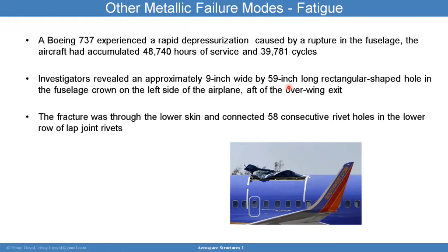And so Southwest Airlines' business model is to fly quickly, many times a day, short trips. And that's how they can make a profit compared to other airliners and also sell the tickets for quite inexpensive. As a consequence, you get many more cycles with the Southwest airliner compared to other airliners, and that's why this failure mode was seen more in the Southwest airliners compared to the other airliners. So I hope that makes sense.